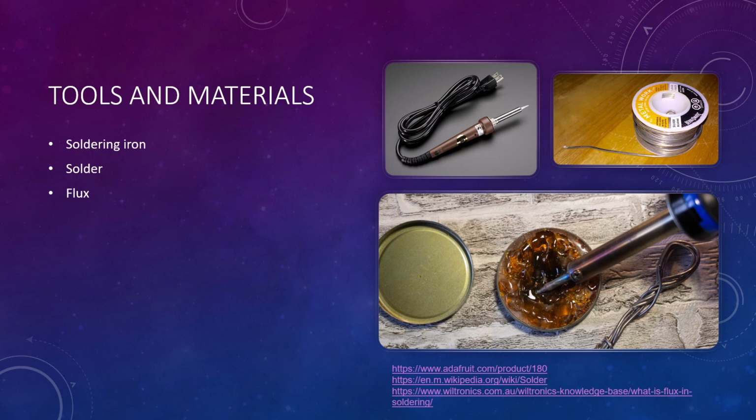There are many different types of solder, and it's important to use the right one for different applications. Some types of solder include plumbing solder, lead-based electrical solder, lead-free electrical solder, solid wire solder, rosin core solder, and many different thicknesses. Lead-based solder is easier to work with. However, lead-free solder is safer to use. Rosin core solder is better because it sticks to the flux more efficiently. The thickness depends on the scope of the project.